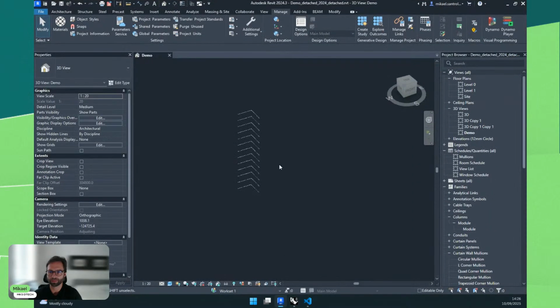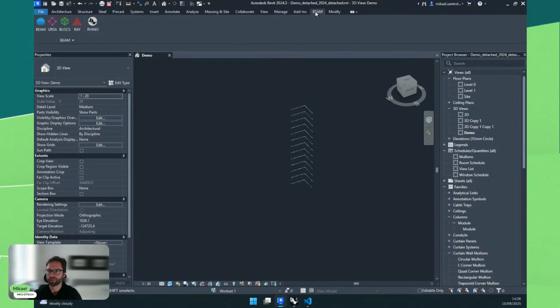Let's switch to Revit, okay? So now we're in Revit, there is nothing here. And in my ribbon, I have my BEAM tab and all my BEAM tools available here. Also in this drop-down, we can find our About, as always, and also the licensing dialog. Let's use the standard BEAM tool, no? That allows you to import geometry. It has maybe fewer dedicated commands compared to blocks, but it will also import blocks.